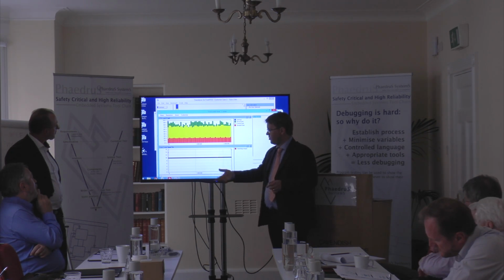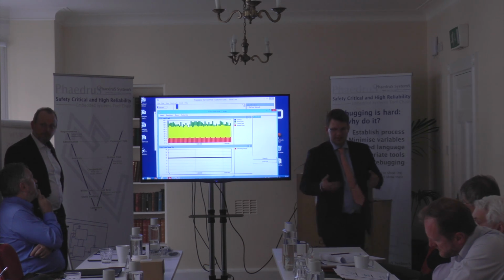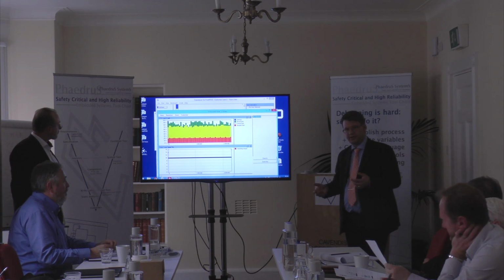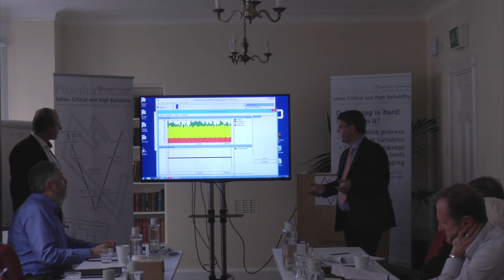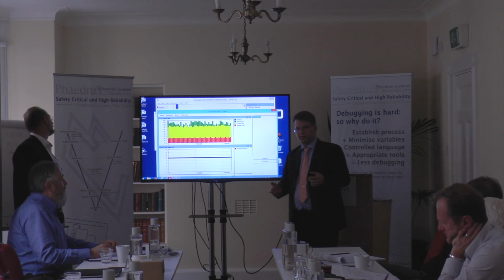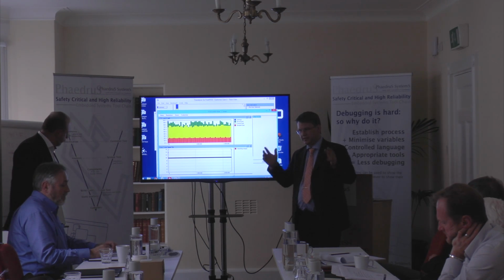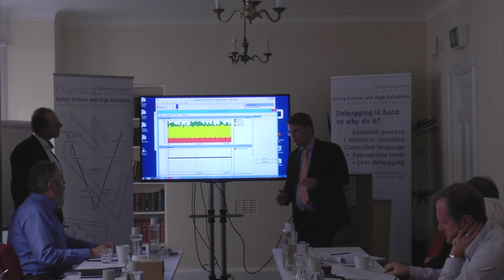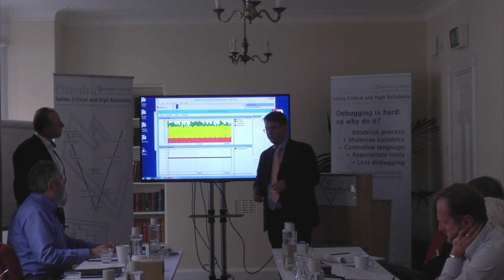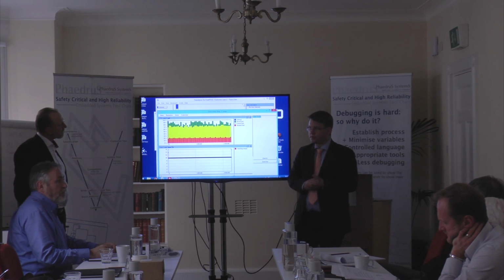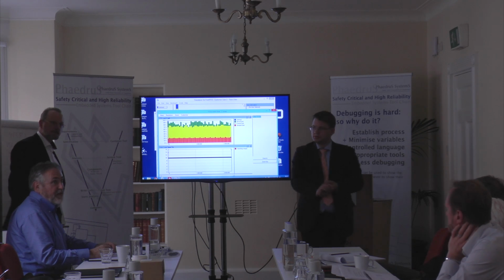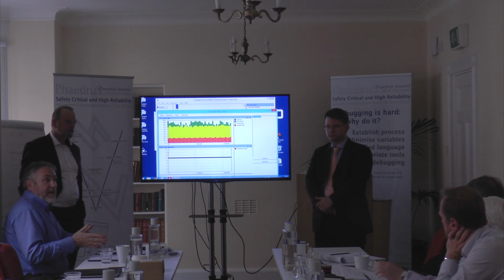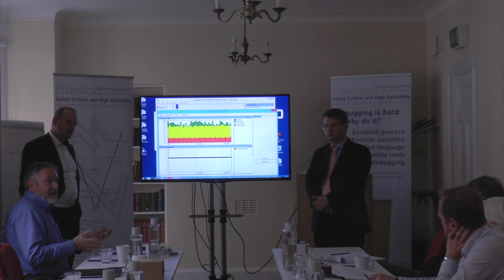But we can still record, in practice, for an unlimited amount of time, as long as you have disk space. As soon as we have this capability of scanning a huge trace and taking out the right chunk and loading it, you can work with traces measuring hours and hours. Traditionally, this has only been possible with fairly heavy-duty JTAGs with a separate ICE connector, a separate trace connector, and actually implementing trace coming out of the chip itself.